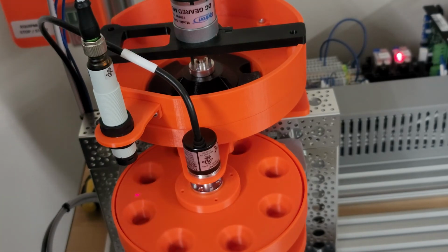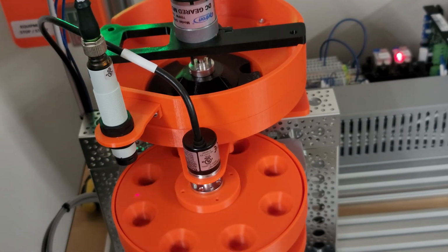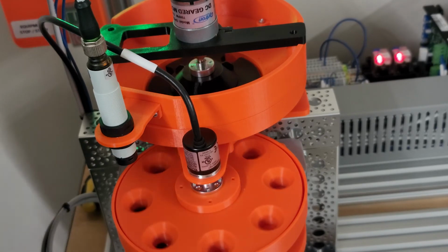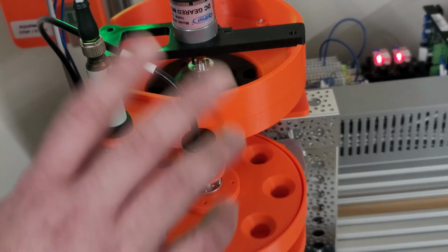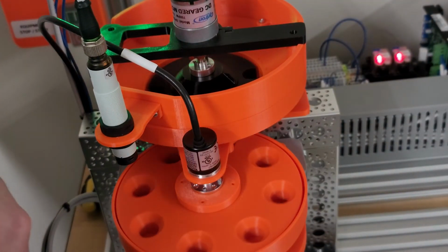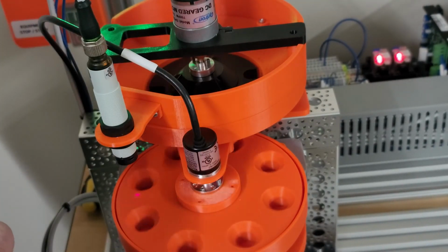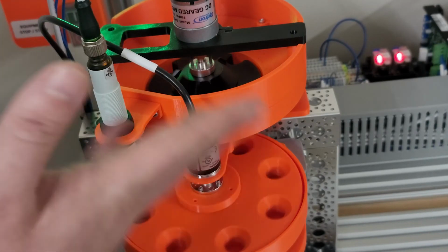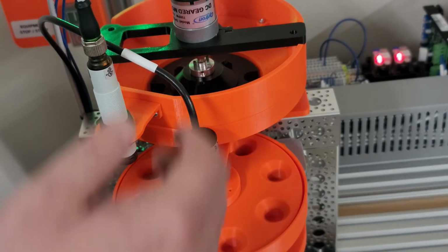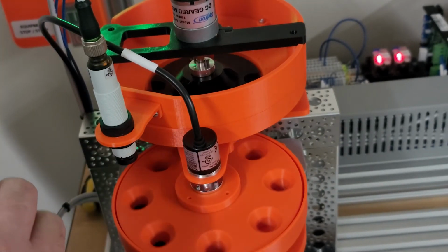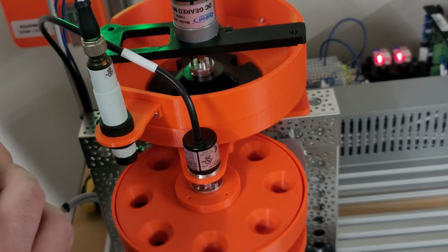If this works with what we want as far as the action we want to occur, I may leave it alone, but we will have to see about that. It's right on the verge, so I may increase it maybe 1/4 of a second or 1/2 a second. Anyway, what we want to do is make sure that when we load marbles in, we're moving at a reasonable enough speed that the marbles will exit the indexer before they have a chance to jam. So even though the two motors aren't moving at the same relative speed, it's okay for this experiment.